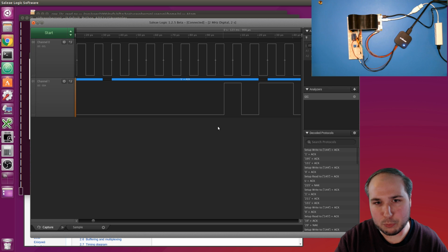Now for the value of 1, you have to go into the datasheet for the ADS1115 to understand what it means. This is specifying the register of the device I want to talk to, and a value of 1 is actually the configuration register. That's a register on the device that says how the ADC should be configured, like what gain it should use and how many samples it should take per second, and that's what I'm actually doing here.